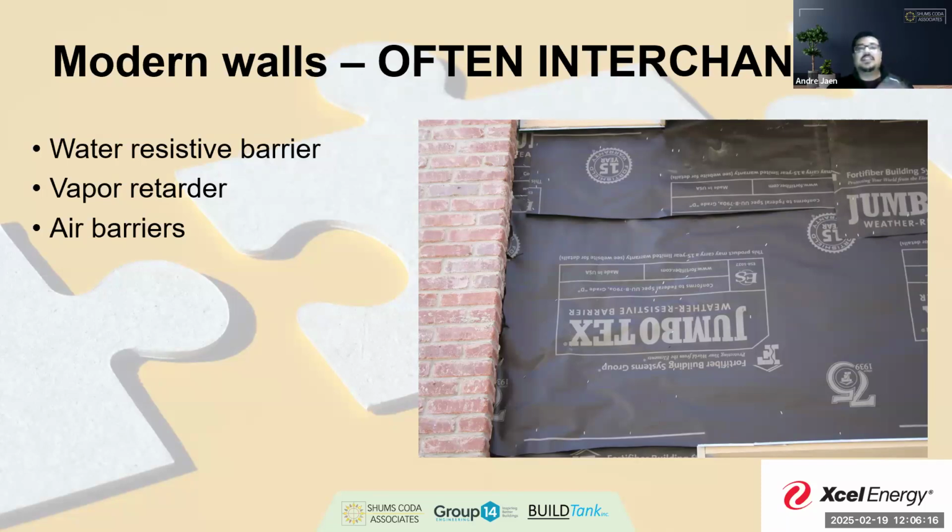Because you get a designer who sees very clearly maybe how this layout is supposed to work and how this entire wall assembly is supposed to come together. And then as you get other trades working together, who's sealing for what? Who's sealing for your air barrier, right? If your electrician's sealing their penetrations and your plumber's sealing their penetrations and your tinner is sealing theirs, then are we being very clear about what product is being referred to as the air barrier and being identified on the plans as the air barrier?